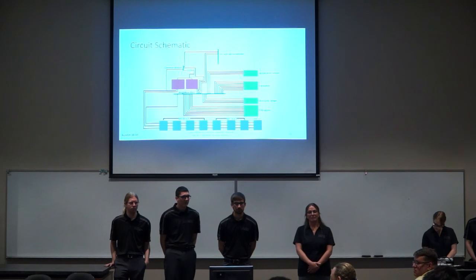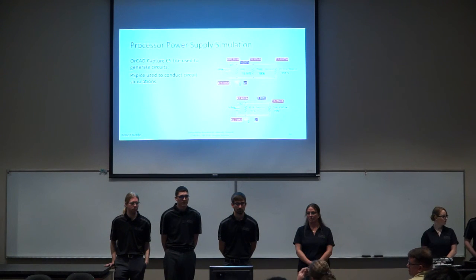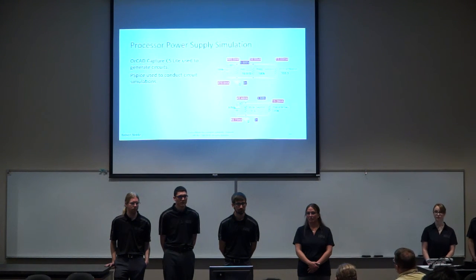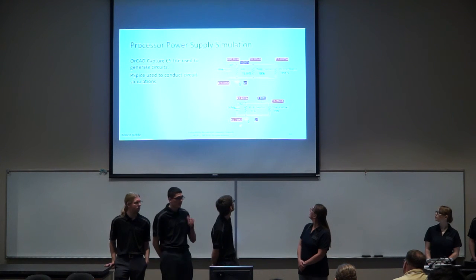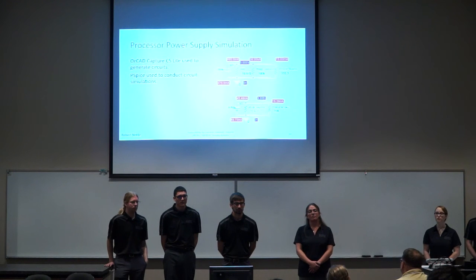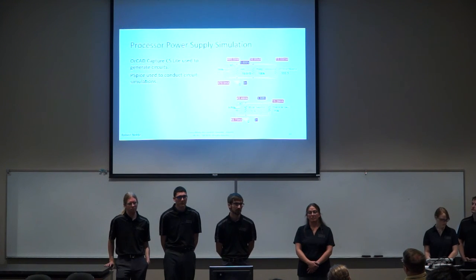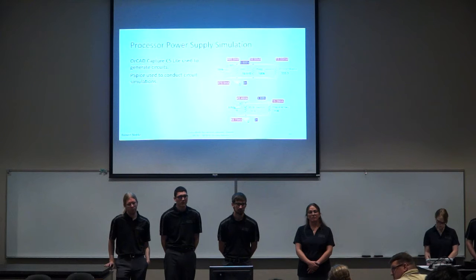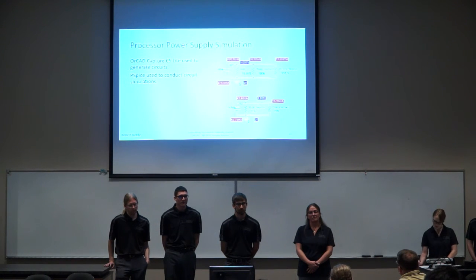And that gets back to, if you go to slide 64, what Professor Skipper's talking about is, will you be able to supply that 60.73 milliamps from the onboard power regulator? We have not verified that. And I have BeagleBone Blacks with blown power regulators, which would suggest no. So once again, you're going to need additional components to be able to handle that 3.3 volt load, which are not represented in your block diagrams, which are not represented in your bill of materials.